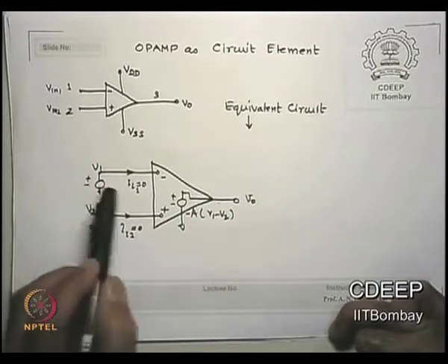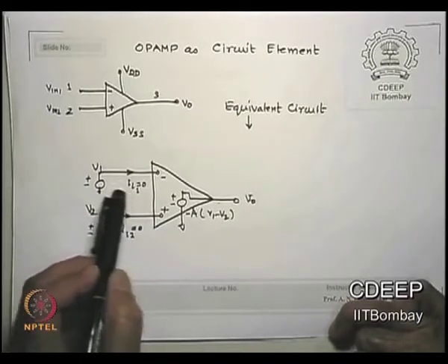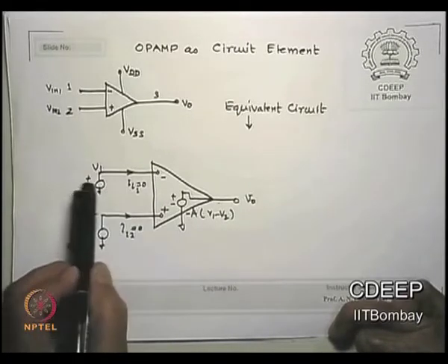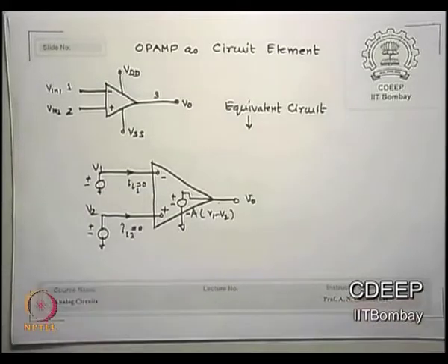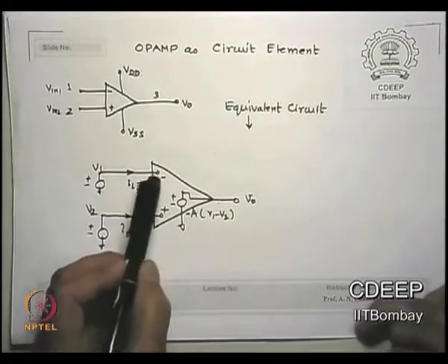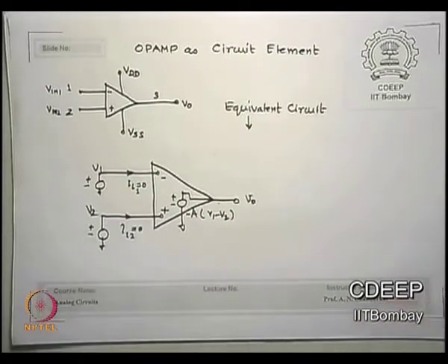Please remember what is the equivalent circuit I am now saying. A typical OPAMP. I am now saying if there is my input voltage, there is no current inside the minus terminal. Why do I say so? Or no current in the V plus terminal. Why do I say so? I can say so, okay, I will come back to it.